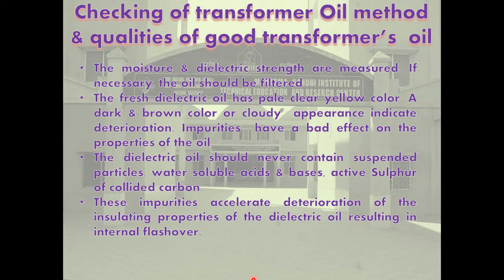The dielectric oil should never contain any suspended particles, water soluble acids, bases, and active sulfur or colloidal carbon. The impurities accelerate deterioration of the insulating properties of the dielectric oil, resulting in internal flashover.